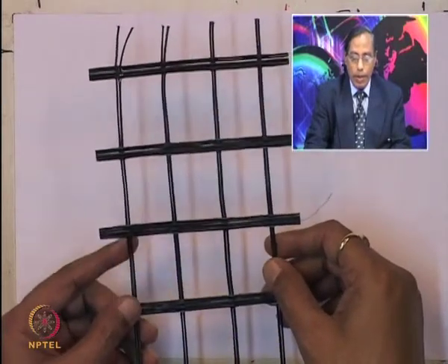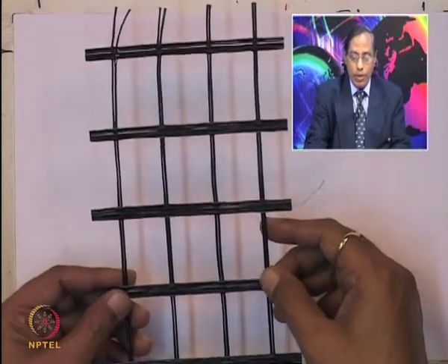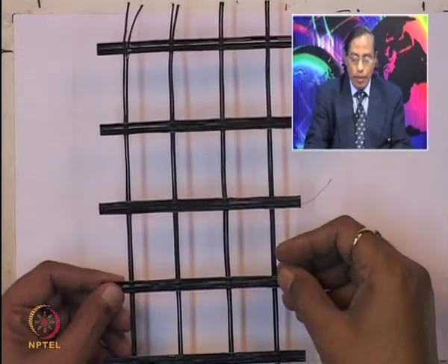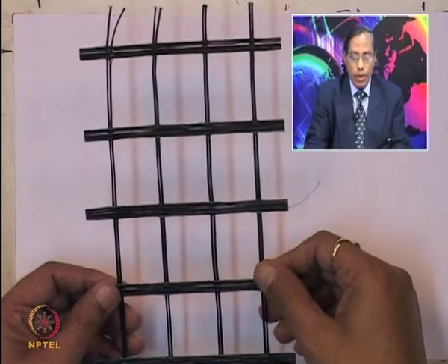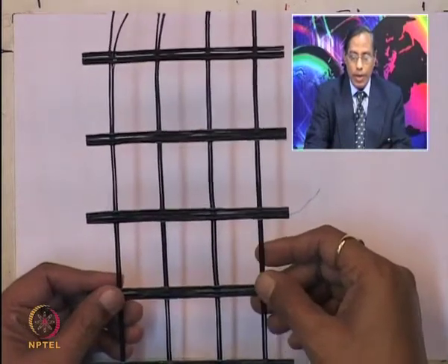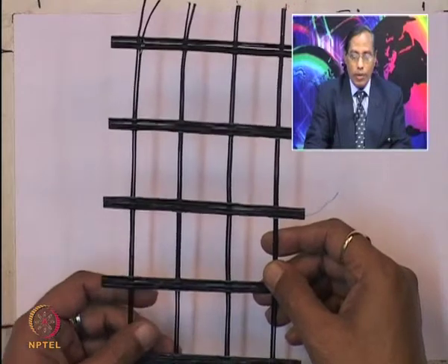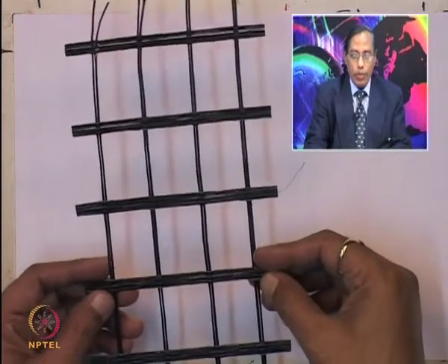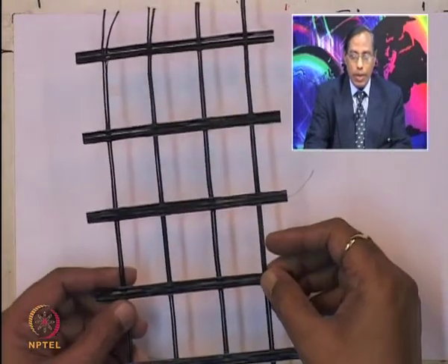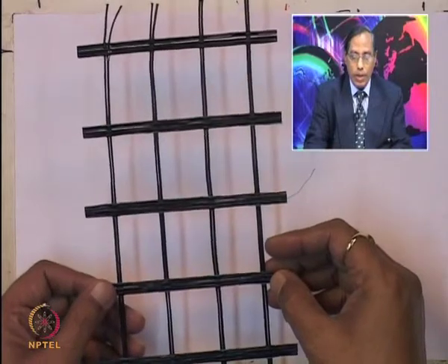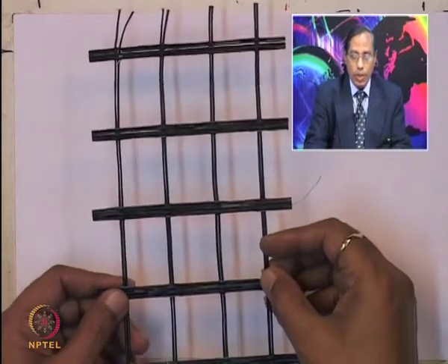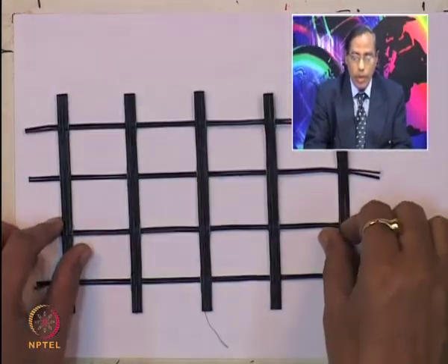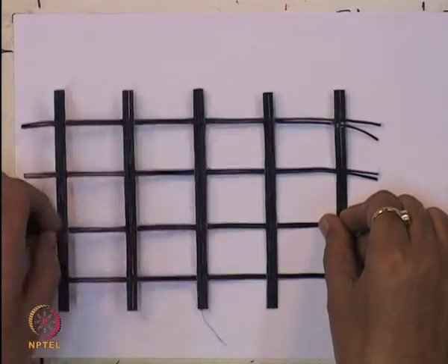You can have different strengths and different types of geogrid material. It has a tensile strength in the machine direction as well as in the cross machine direction. You also have to take care of the elongation of the geogrid in the machine and the cross machine direction. So we will mainly use this kind of geogrid material in part 1.